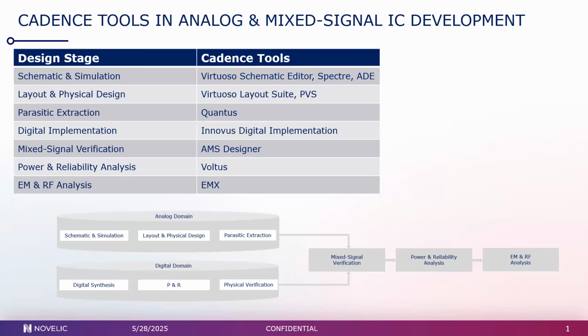are correct, etc. And we also have the LVS tool, that is layout versus schematic, that is used to compare the layout to the actual schematic and see if everything is as drawn in the schematic. If there is any discrepancy, we get the error and we can fix it very quickly this way.